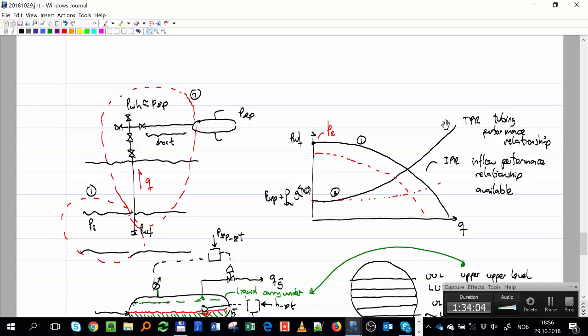And you see that that simple example of the horizontal pipe with the two ends allows me to create a curve to represent this part of the system and a curve to represent this part of the system. It's just an analogy, but it's very powerful. Now, I know that if I put these two elements together, it's going to operate at a unique rate. I will have only one unique pressure here. They cannot have two pressures when I put these two together.